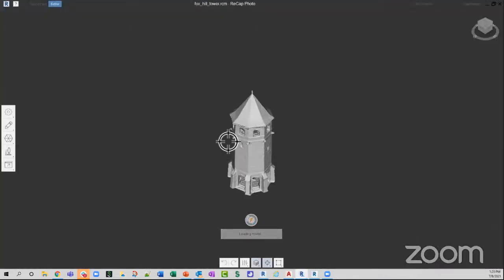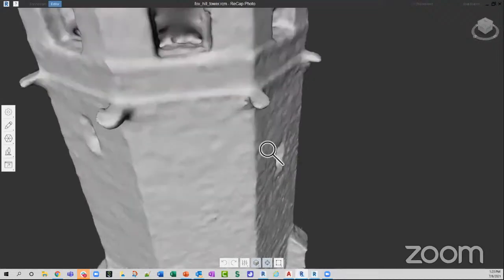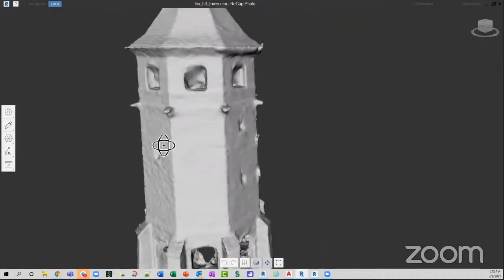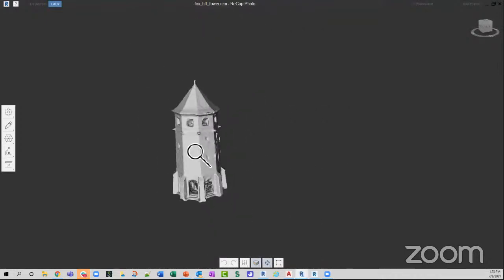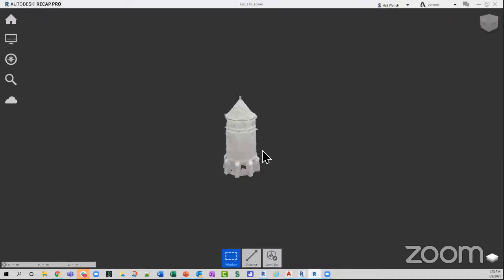you're going to see that it looks more like a clay model than the actual representation. So I don't see all those materials. I don't see the stone. I don't see any of the brickwork. And so why is that? Right. So the reason for that is, unlike that utility plant scan that we just saw, this is a drone flight, so it doesn't have those 360 photos attached to that flight, and that's really key to getting the material, the color associated with that mesh file.